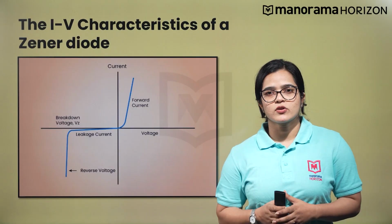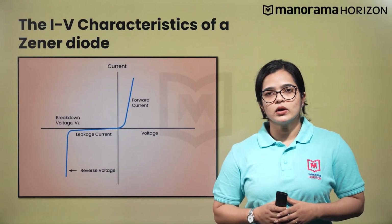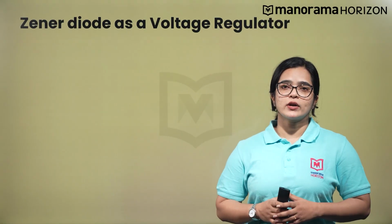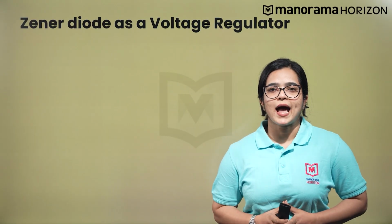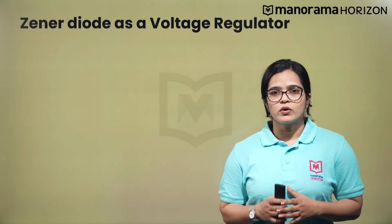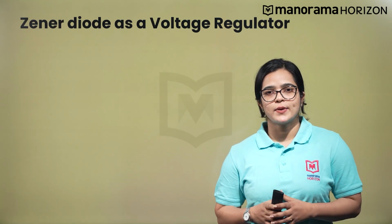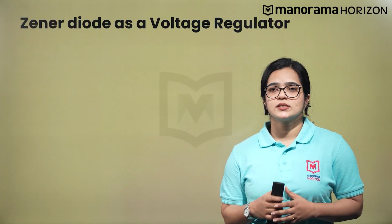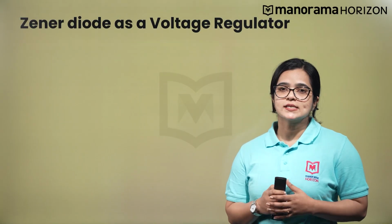The emission of electrons from the host atoms due to the high electric field is called internal field emission or field ionization. This most important characteristic of a zener diode, as stated before, allows it to act as a voltage regulator in a circuit. The voltage that is dropped across a zener will not exceed its breakdown or zener voltage even if the voltage or current in the circuit increases, which is what is depicted in the IV characteristics curve.